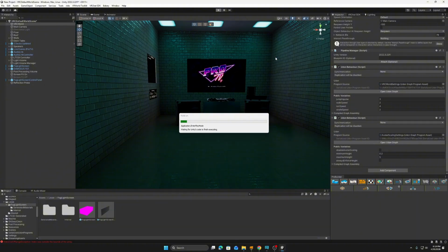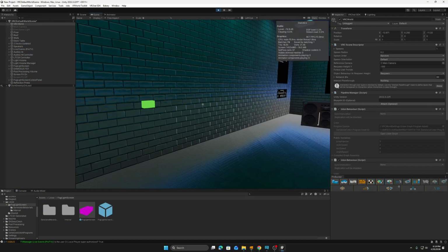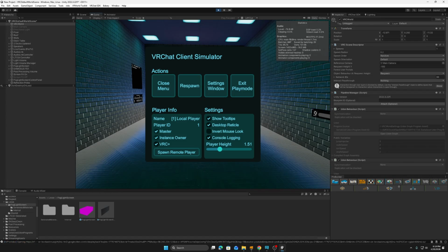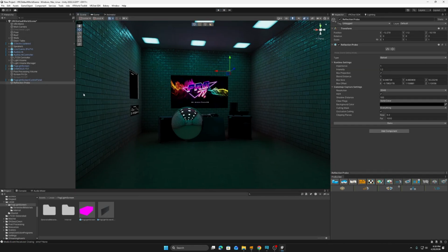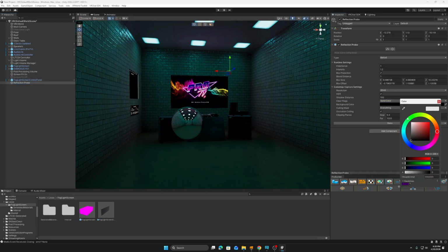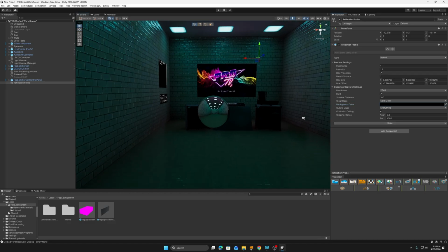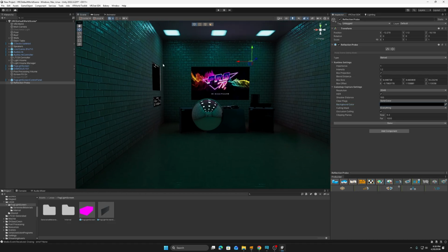And it's still optimized to an extent. Oh, hold on. One thing that I missed, make sure when you toggle environmental stuff back on, go to the reflection probe, change it to a solid color and change it to black. That way it's not going to take anything from the skybox. So now that that's a thing, and then obviously redo the reflection probes. Go to play mode.